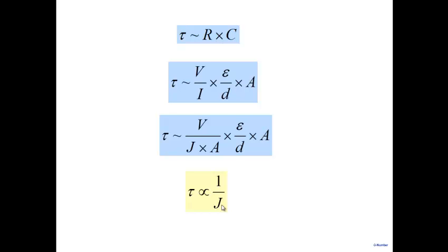So as you increase the current density, in many cases you're able to reduce the delay here. That's why, and this is very simple, you may have a term here which is a constant. So after a while, as you increase J, tau falls and then becomes a constant. Okay, so this is simplistic, but what it is illustrating is that as you push current density higher, the delay drops. So that's another reason why we want to operate a device at higher current density.